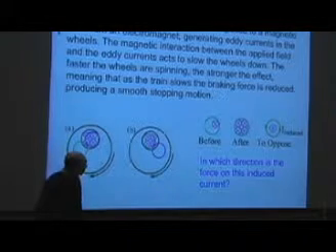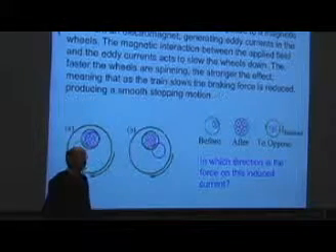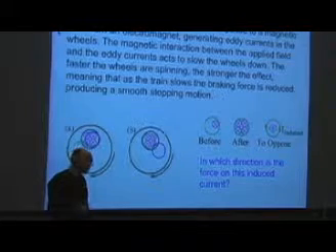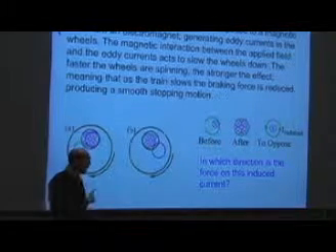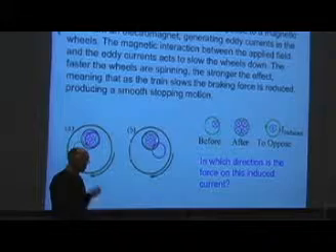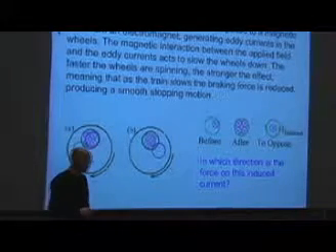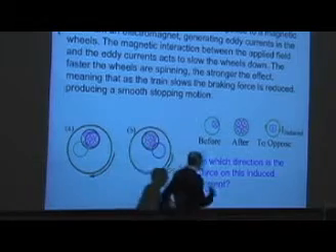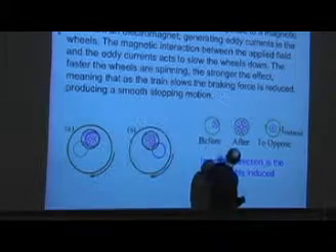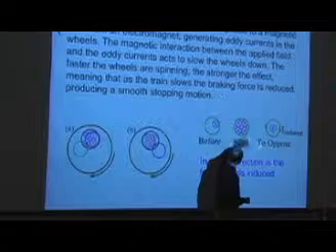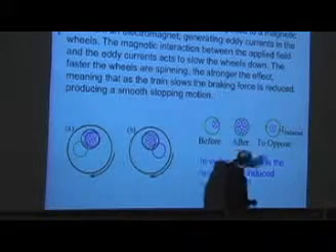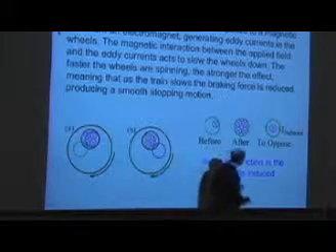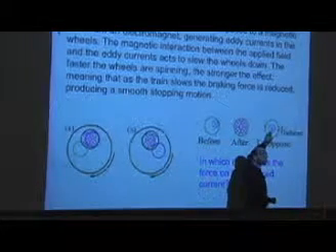And then the two opposed picture, it's a two-step process there. First of all, you draw the field that the loop itself creates. And in this case, it creates it by running eddy currents around that region of the wheel. So the first step in that process is say, okay, there's a change between here and here. To oppose that change, that part of the wheel actually runs an eddy current around itself to create this field here. So that's where you start in this picture.